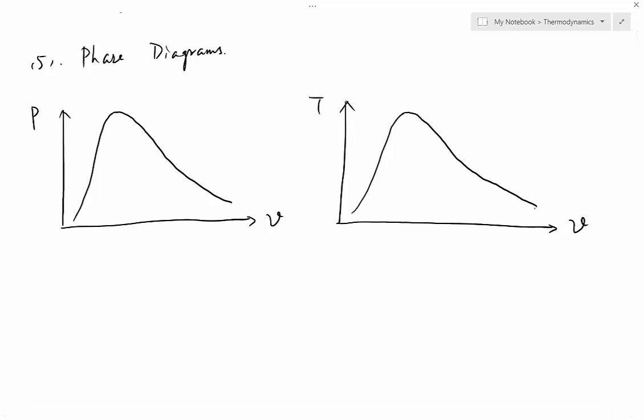Okay, on a P versus nu diagram, we have something called a constant temperature line. How do you sketch a constant temperature line? Here, you have a curve. Remember this is a curve, it's not a straight line, going down. And then you have a flat line within the dome.